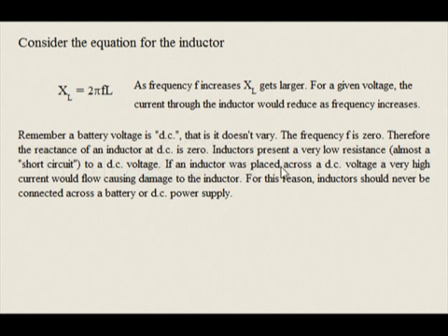If an inductor was placed across a DC voltage, a very high current would flow, causing damage to the inductor. For this reason, inductors should never be connected across a battery or DC power supply.